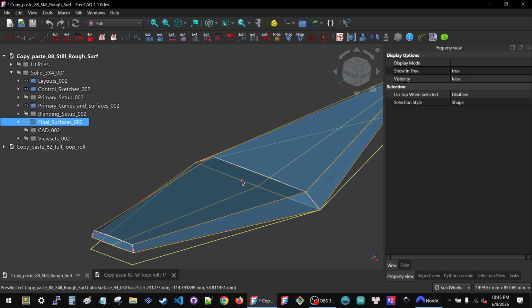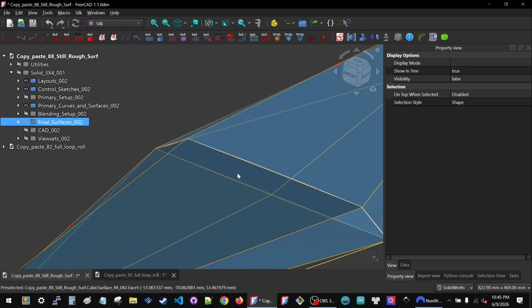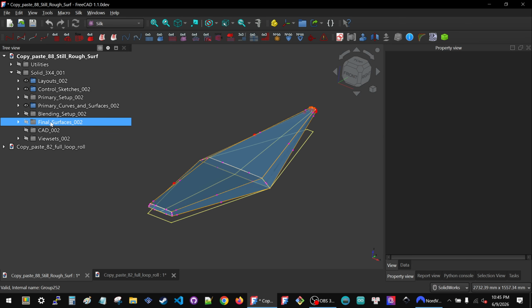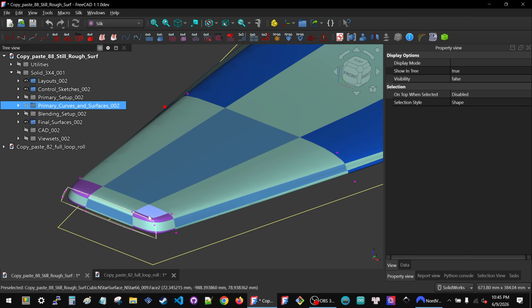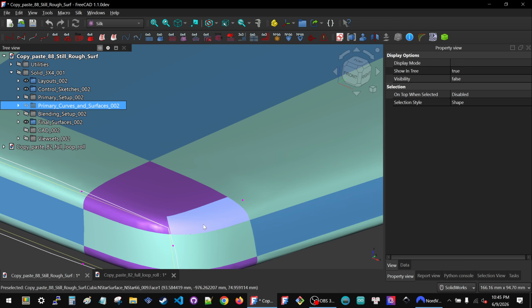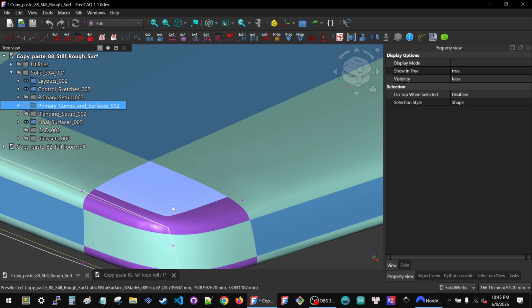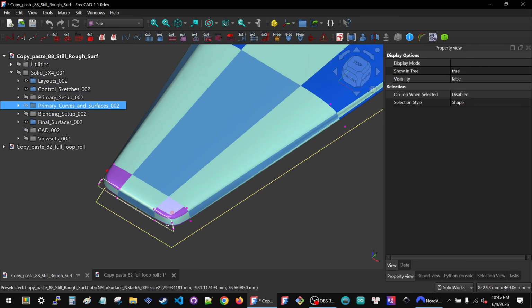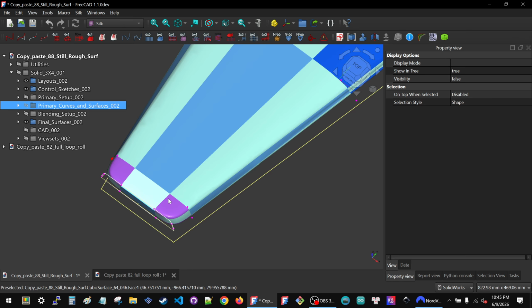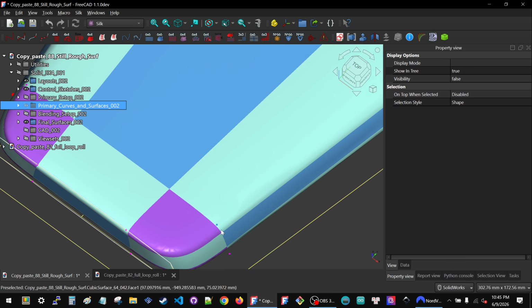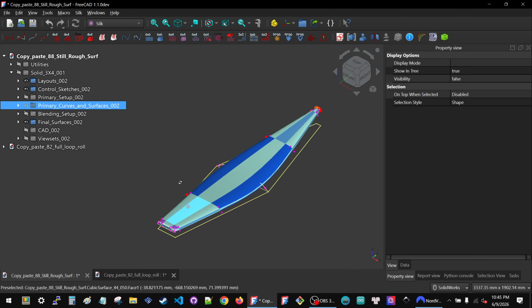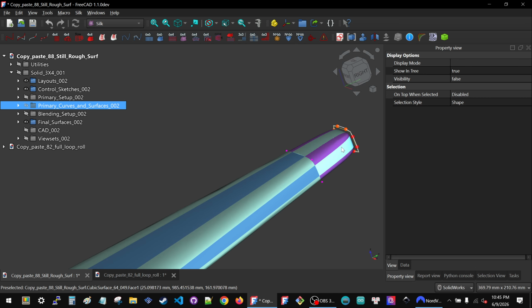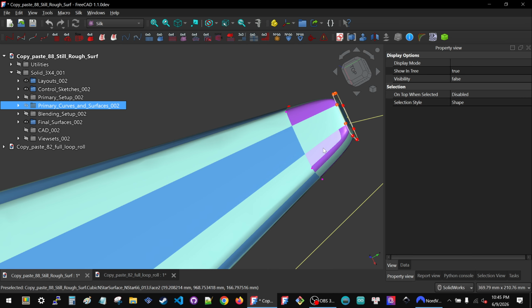But what else? What can we do before we do that? If you remember, I said that these preview blends are all screwed up, and they even caused some crashes in FreeCAD when made into a solid. How are these supposed to work? Well, the important thing is that the three sides should be fairly equal. It should make kind of an equilateral triangle. So this is way too stretched out.